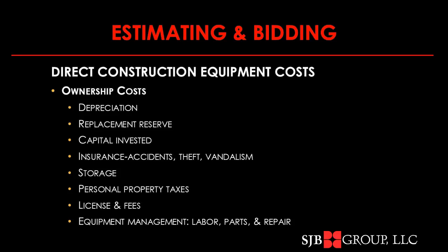The cost of ownership needs to include the cost of money, the amount of interest you paid in carrying the loan to buy the equipment. It needs to include the various insurances that you'll have to buy for accident, theft, and vandalism. You'll need to include the cost of storage, and one aspect of that is the rent, the notes you're having to pay on that piece of equipment when it's not even assigned to a project. That cost needs to be recovered somehow.